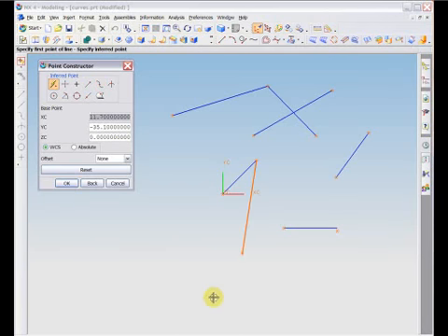Other constraints exist for basic curves as well, and are similar to those shown earlier. However, note that here, with the intersection method, as the command line tells us, both intersecting entities must be chosen, rather than just the intersecting point. Choosing Cancel will close the Basic Curve dialog box.